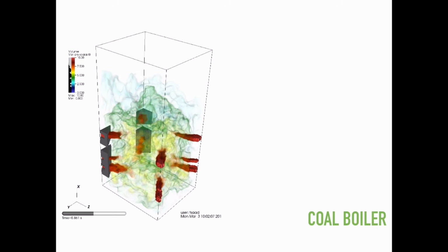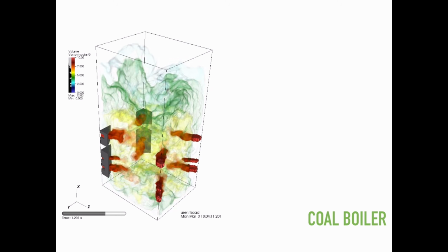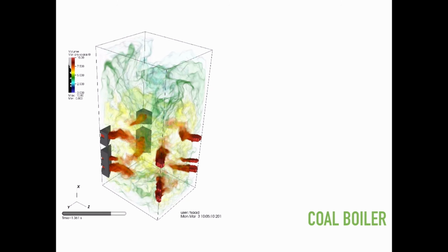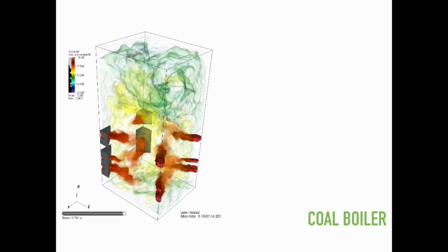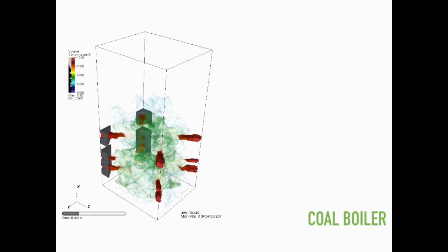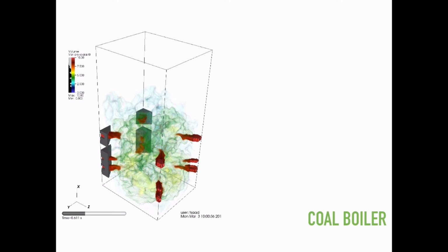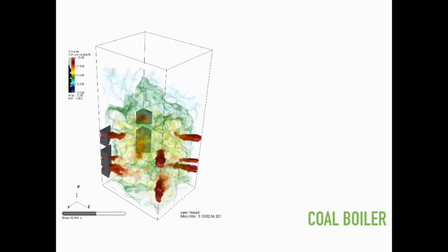As they come in, there is heat in the boiler, just like because we're getting it started. These coal particles devolatilize, they emit gases, and then immediately the gases burn and generate more heat, which devolatilizes the new incoming coal particles, and so on and so forth. But we're looking at just the flow inside the coal boiler, and the exhaust is way up there.